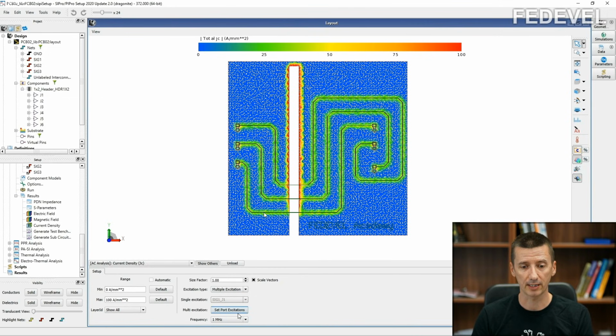So this is one of the reasons why you really don't want to route your signals over a gap in ground planes. This is one of the reasons why you really would like to be sure that you have nice and continuous return current path under your tracks.